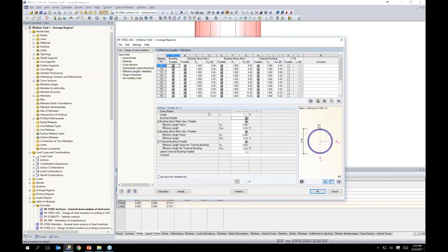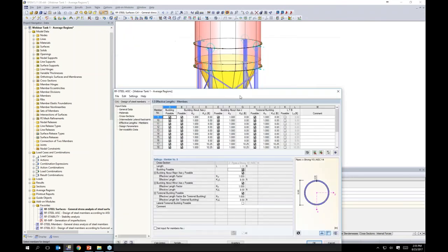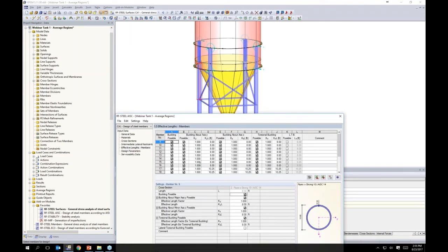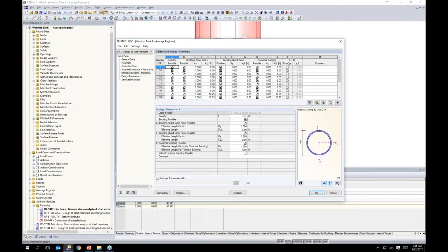The effective lengths are strong and weak axis buckling and torsional buckling, and for this, because we are designing per Chapter C, the direct analysis method from the AISC, we can leave our effective length factors equal to 1.0. The unbraced lengths will default to the full member length. So for example, this is why I created 2 column stacks here, so that the program will refer to the unbraced length as 8 feet as opposed to the full 16 feet, because I felt as though the strong and weak axis was braced okay with the addition of these horizontal beams. Torsional buckling, same thing.